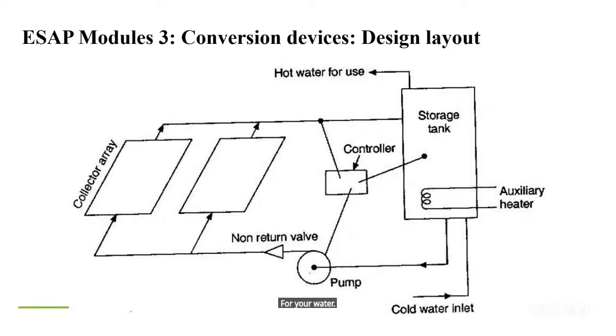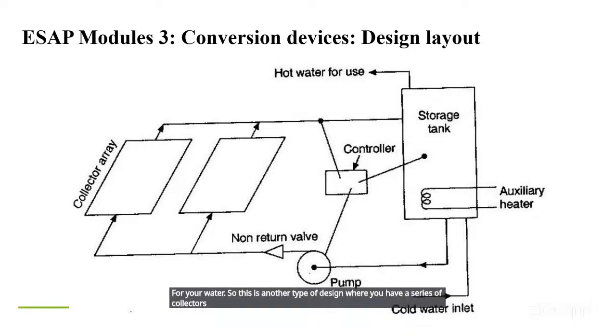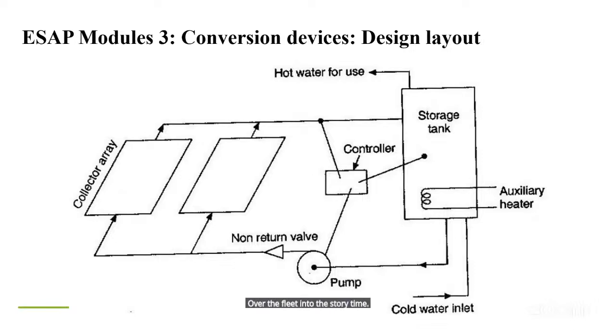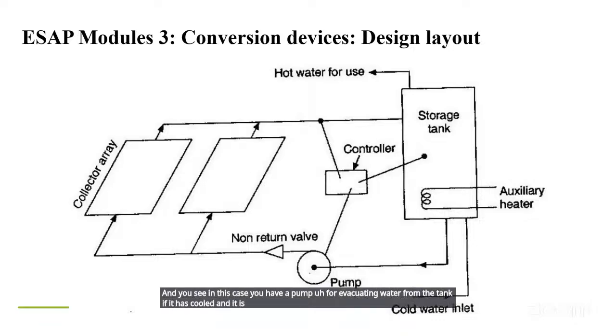So this is another type of design where you have a series of collectors, and then you have a controller to control the temperature and the flow of the fluid into the storage tank. And again, the storage tank is also equipped with a heater in case the collectors are not working. And you see in this case, you have a pump for evacuating water from the tank if it has cooled, and it is channeled again into the collector.